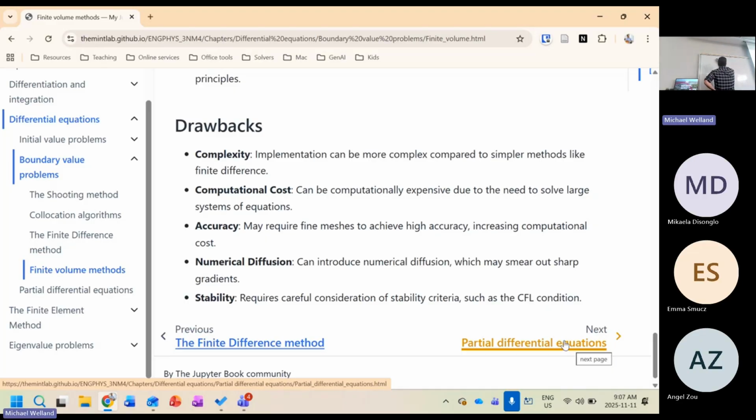Say you're in one dimension, temperature T as a function of x, and you know over here your heat flux J out is equal to 10, right? And you have your thermal conductivity K equal to 1. Just make it easy. When you're doing it through finite difference, you're going to discretize your space. You're going to have to use forward difference over here, or our nifty little trick with central difference, which kind of amounts to the same. So let's just go with forward difference.